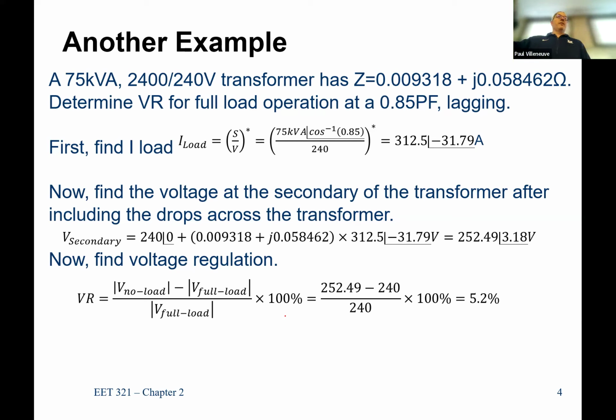A lot of those single phase pad mounted transformers are outside buildings. If you go to some of the dorms, you don't see the transformers outside because they are inside the actual building. It used to be allowed to put transformers in the building because you wanted your low voltage stuff as close as possible to the panel boards, so you could run a lot smaller cable. You had a higher voltage rating, but you could run much smaller cable.